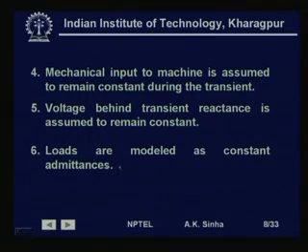Those things can also be modeled in the modern programs, but for our purpose of understanding how we do this analysis, we are assuming that the loads are constant impedance loads, that is, the impedance value we calculate at the voltage level at the pre-fault condition, or before the changes occurred at t0 minus, whatever is the voltage at that time. We calculate the admittance knowing the power, and we use that admittance all the time, assuming it to remain constant.